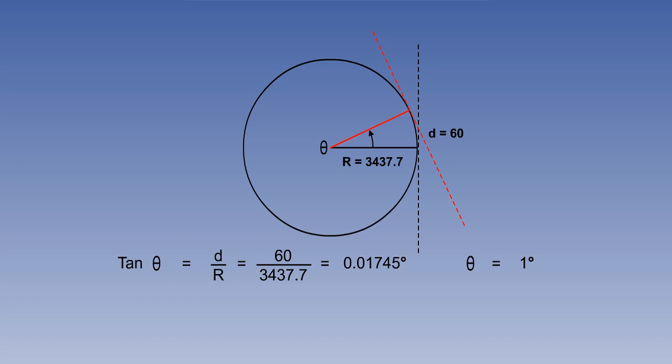However, in reality, it would not be sensible to wait till the aircraft had flown a distance before feeding in a correction to the gyro. The gyro attitude should be adjusted as soon as the aircraft starts to travel. Therefore, instead of using d, the distance gone in the above equation, we take v, the velocity, northwards and use it to find omega, the angular velocity. Omega is the rate at which we need to correct the platform. It will be a value in degrees per hour. The equation now becomes omega equals v over r.